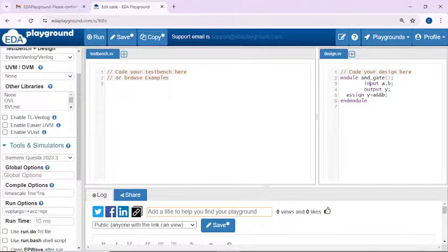This code has the module name. It is the syntax of Verilog, and we have to give the module name. Inside the brackets we have to give the port list, which is nothing but the IO, inputs and outputs. After that you have to give the condition or functionality of the design. The AND gate has multiplying functionality, so I am using assign.